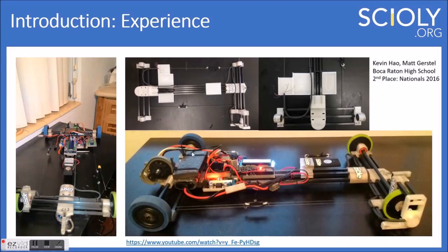The steel brick here, we wanted some more weight over the rear axle just because we were accelerating so much, and we just needed more frictional force, so we just increased the normal force. In retrospect, it might have been better to get new wheels. We used these blue wheels, but they were not as soft as, say, the orange or the green ones, and I'll go into that a bit more later.